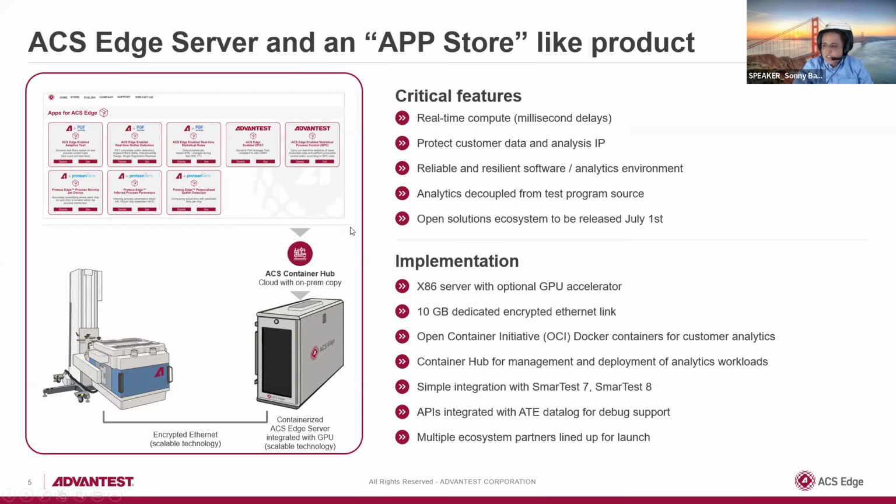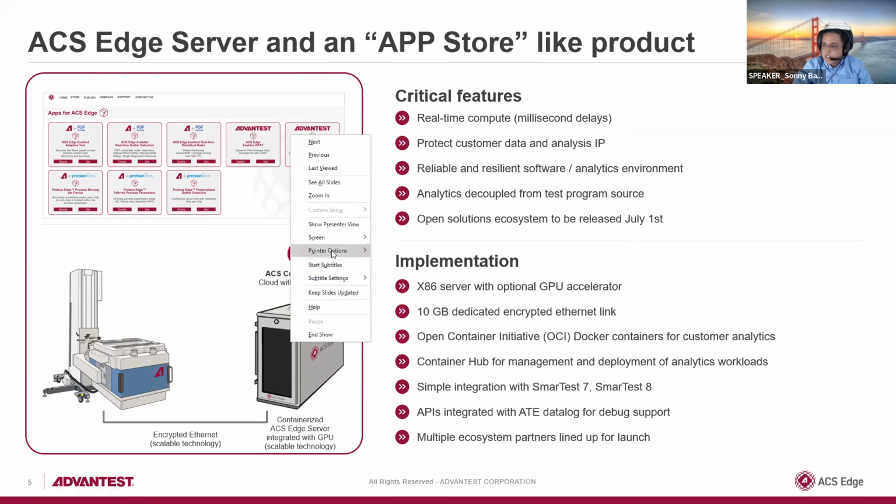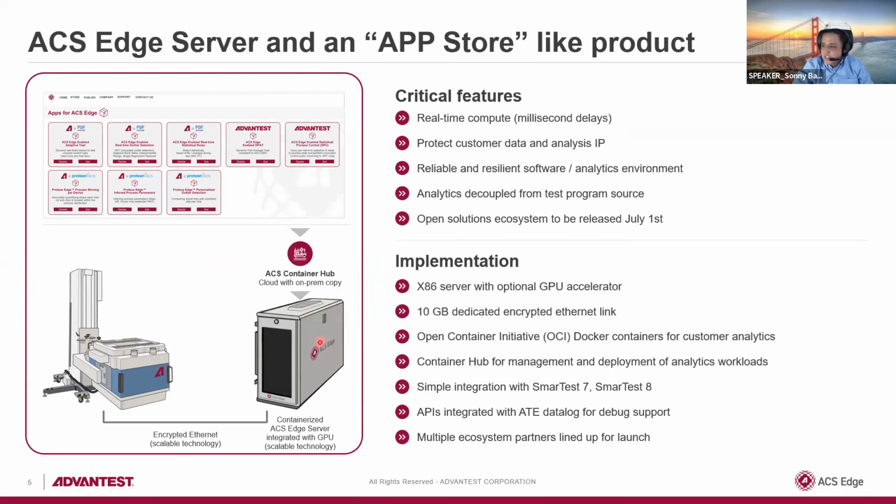The essence of edge computing is that we created this inference server, which, let me use my pointer, this inference server over here is an x86 architecture and has a GPU in it. It's connected by a 10 GB Ethernet link directly to the host controller on the tester. This allows us near real-time compute performance.